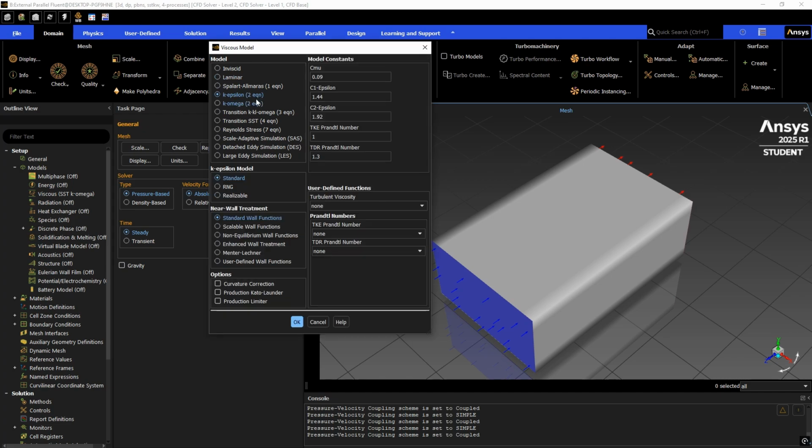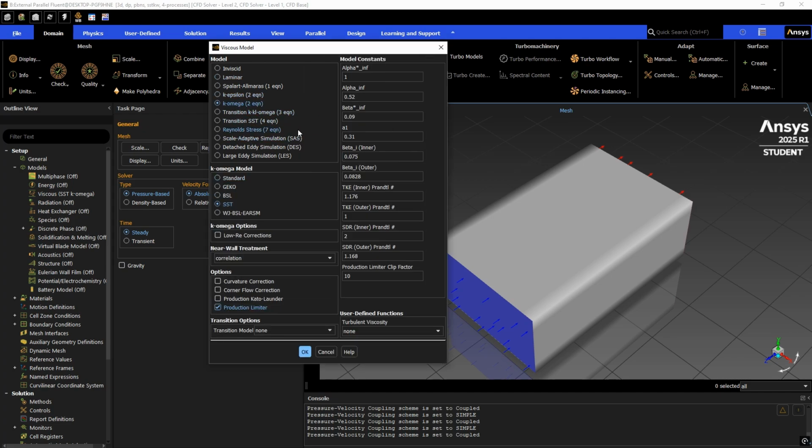And these explanations that I just told you, standard K-Omega near boundary layer, K-Epsilon away from the body, and SST K-Omega as a bit of both, this is a good explanation. You can use this in your homeworks, you can use this in your assignments, and these are acceptable explanations. So we will select the SST K-Omega function here, and we will continue.